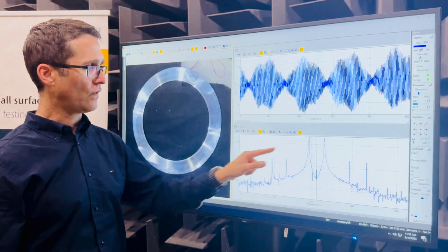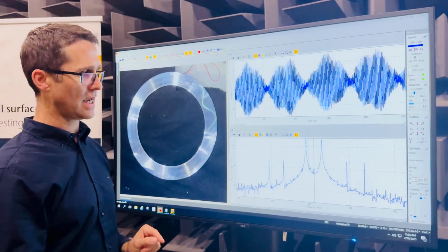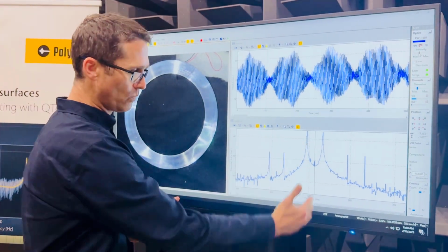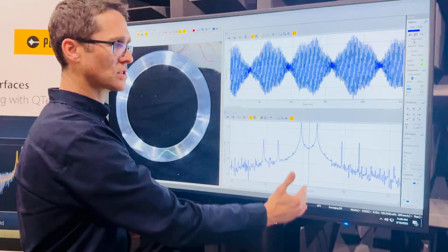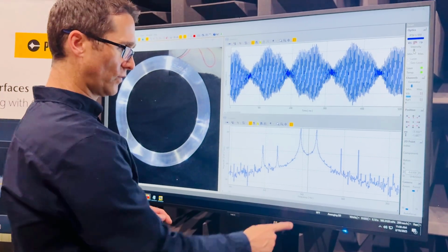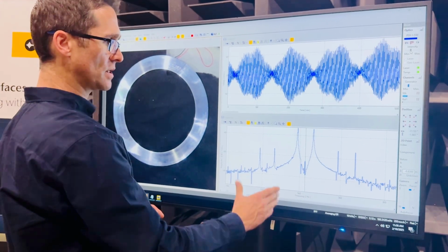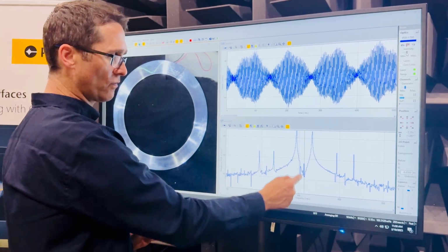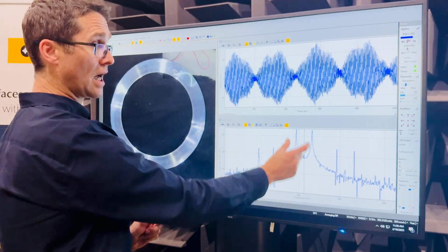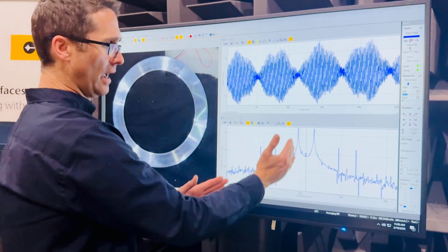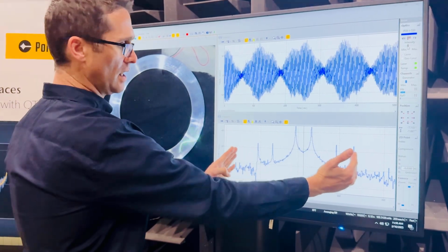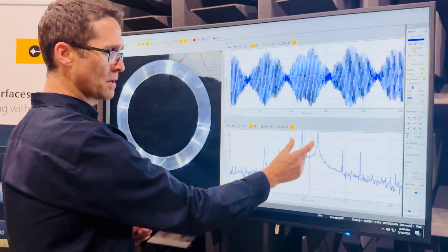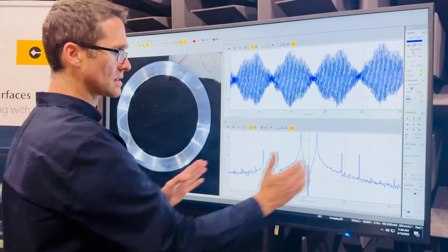If I do a quick fast Fourier transform of these time domain data, you can see the way that we can do that. So our resonant frequency is at this central peak here, 342.6 hertz, as I mentioned. We have sidebands about that primary vibration frequency that are actually larger in amplitude in this case, and further sidebands at other distances away.